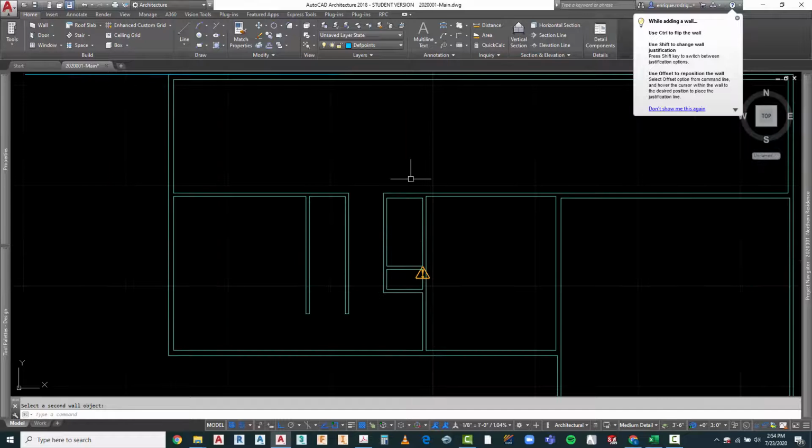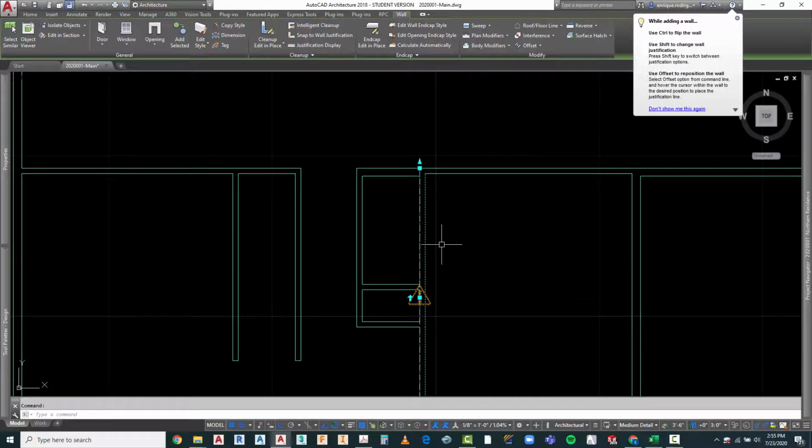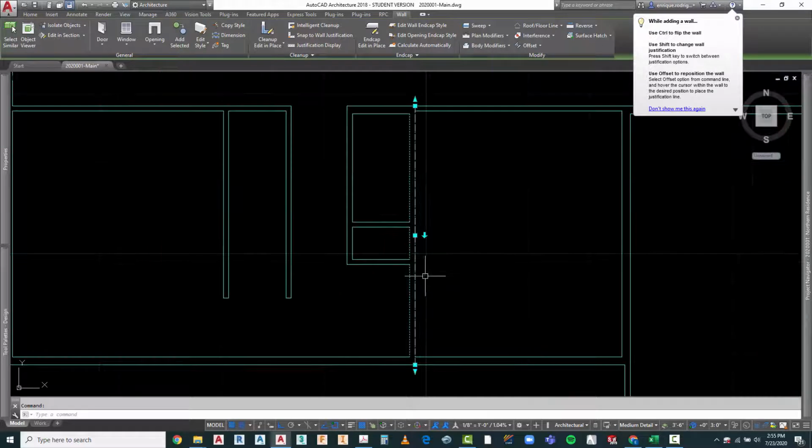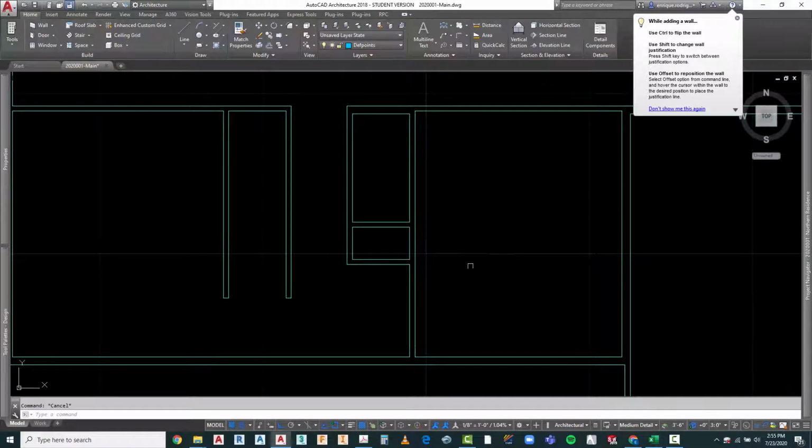and let's see what happens if I fillet this again, if I'm still going to get my errors, which I do. So how do we fix something where we can't seem to fix it at almost any time? Sometimes what you can do is flip that from one side to the other, notice, and that might solve the other problems. Other times you may need to do what's called a cleanup.